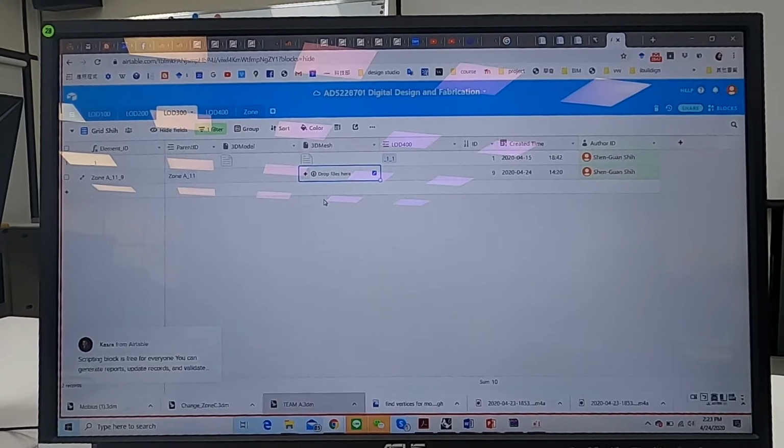So this is a shop drawing, and maybe somewhere you need to punch holes or whatever because you want to make the lock. So you draw a shop drawing for this panel, and then maybe a shop drawing for this panel, or if your way of fabrication is you cut a piece of aluminum sheet like this, and then you ask the factory to fold this line for some certain degree. Okay, so you need to do this as a shop drawing and then put it on the database.